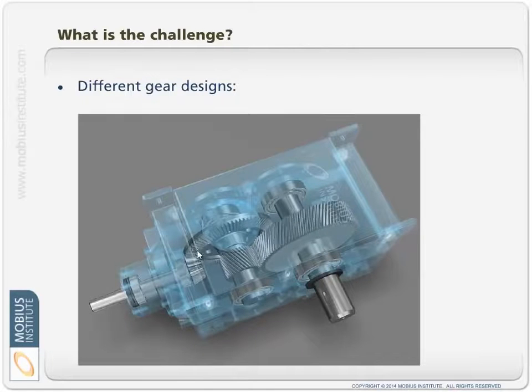In this case, we've got a bevel gear which creates more axial vibration, and a spur gear which creates more radial vibration, and we've got certain measurement points that we can use, so we just need to be sensitive to what the forces are like, and therefore you may, in this instance, take an axial reading as well as a radial reading.